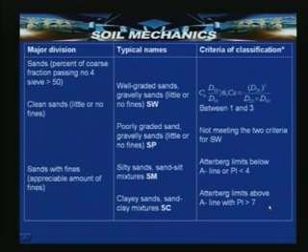That means, if you take the plasticity index and liquid limit and it falls above the A line, because the plasticity index is greater than 7, that is clayey sands and sandy clay mixtures. So, the SC group indicates clayey sands or sand clay mixtures. Silty sands, sand silt mixtures are indicated by SM.